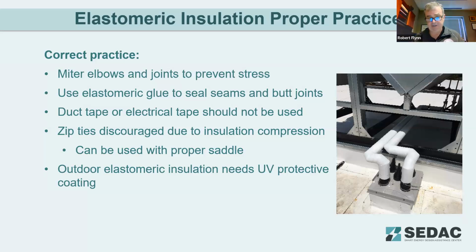And one more thing, Sean, is when you put the rubber glue on there, you put the glue on both pieces. If you're going to insulate from rubber to rubber, you have to put the rubber insulation glue on both pieces of insulation, not just one, and then glue it on. It butts to the glue, so the adhesive meets the other piece of adhesive. If that makes sense.